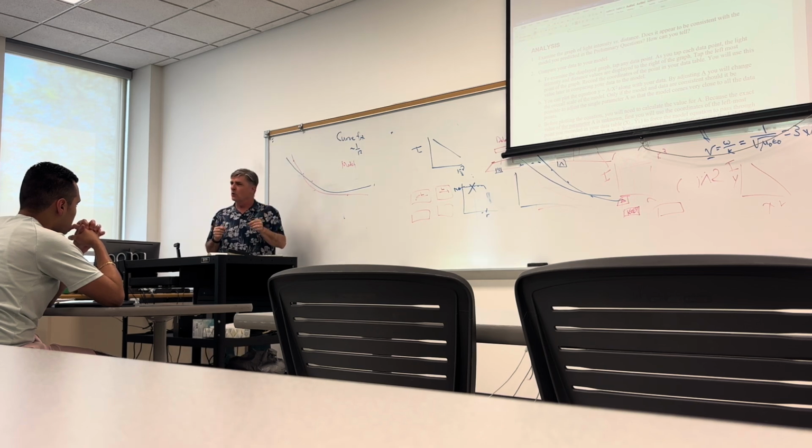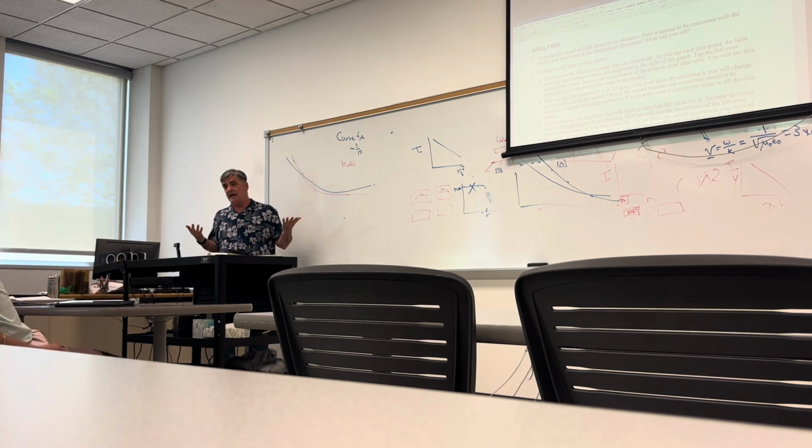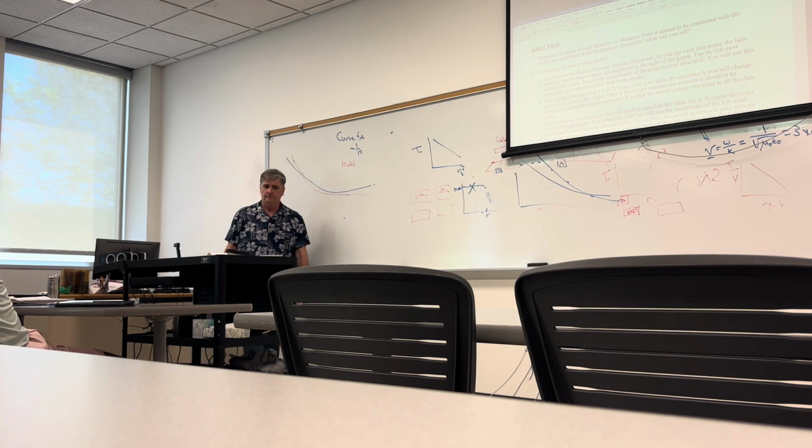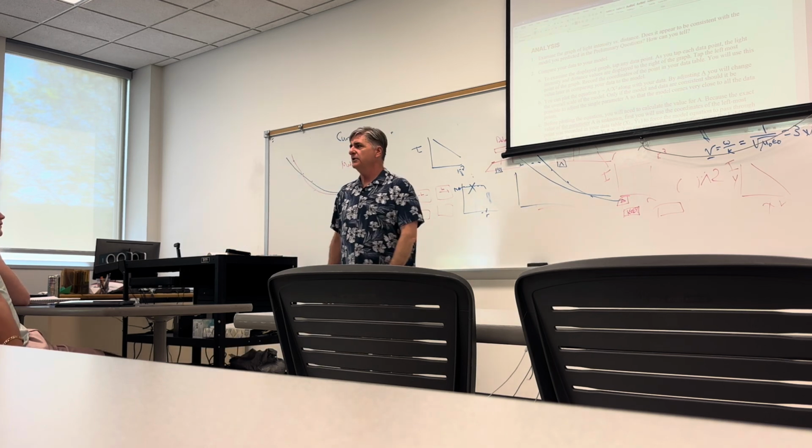I can't possibly record every value accurately. I don't have the money to make an instrument that's accurate. So I have a 2-point or a 3-point accuracy depending on how close you are. And the manufacturer guarantees, yes, if you do a 2-point, those points will be within so many 9s of difference, as we call it. Basically, statistically negligible off. But every point in between, I can't guarantee because I can't guarantee a perfect instrument that scales linearly or quadratically or whatever. Makes sense? There's a physical limitation. So that's my guess why they do it this way.